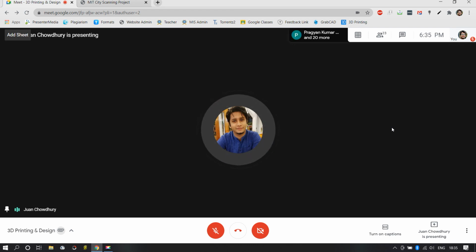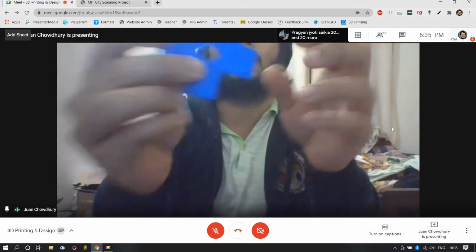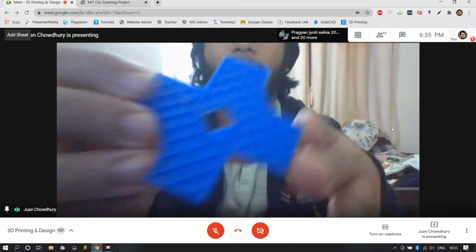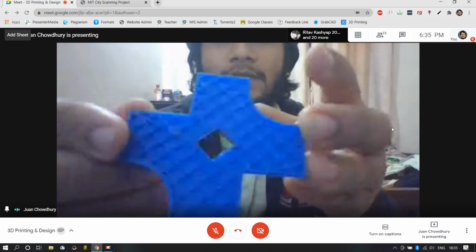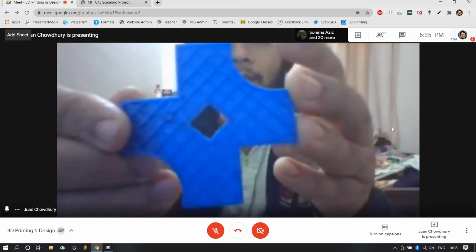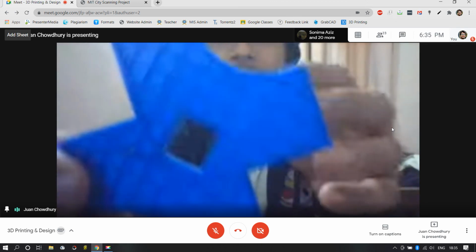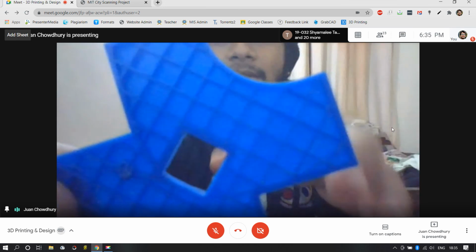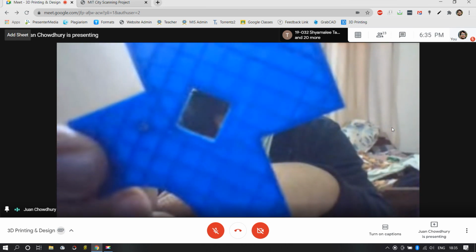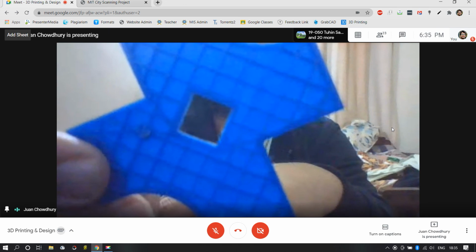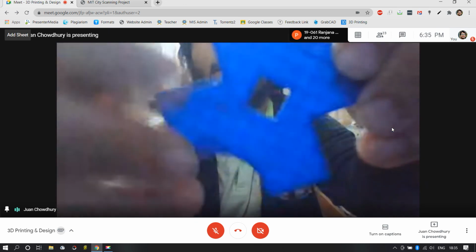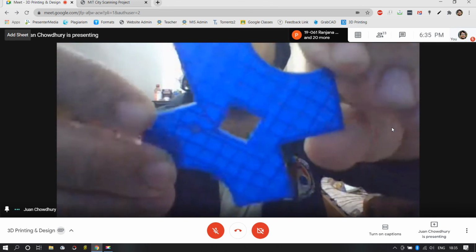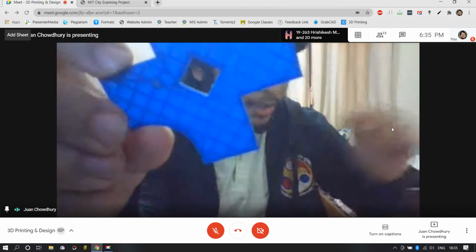With a very low infill density, you will always have the problem of delamination. As you can see, we had a very high fill density over here, but the interior of it was actually very light. This was the cover plate to the design. Now you can see that the whole pattern is broken down into smaller sections. They go about printing these smaller sections once in a while, and then there is this small triangulation of the STL that you can see within the component. By the way, this was a failed component because of power disruption. So we could not complete it.